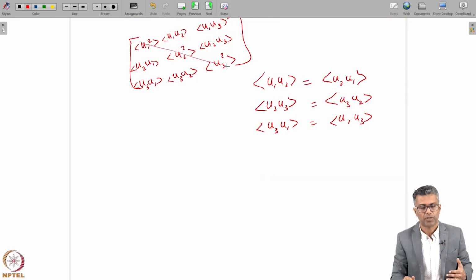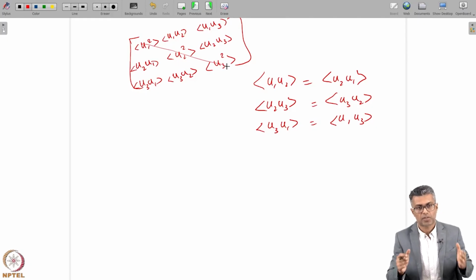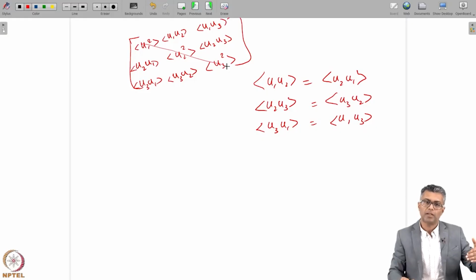It's like a pressure term, a scalar, whereas U1, U2 are shear stresses. In a stress term, generally the diagonal components are normal stresses, and the off-diagonal components are shear stresses. This is what you would have in a regular stress term, right? And that is what we are trying to equate to a Reynolds stress tensor as well, just like we would do, for example, for a viscous stress tensor.